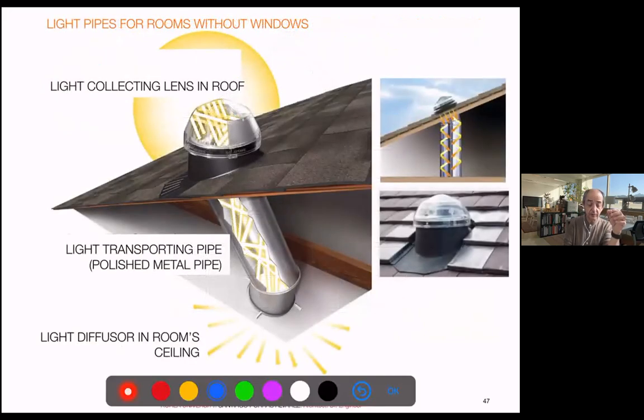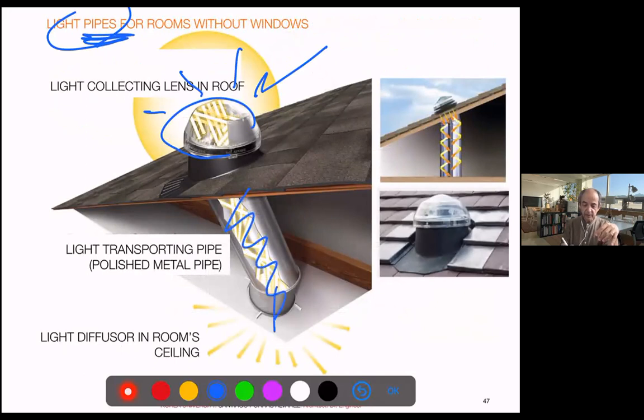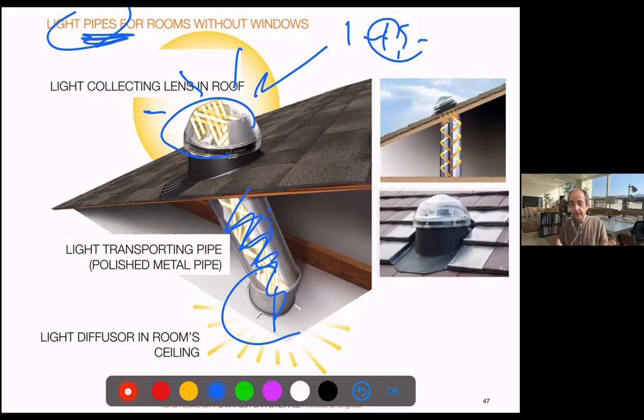Another thing which is interesting is light pipes. Over a small distance, you may have a lens which collects the light from the outside, and a very reflective pipe, which may give light to a room between 1 and maybe 4 or 5 meters from the roof, even lower. You have natural light, almost perfect, with the whole spectrum of light. I say almost because many of the light waves are already absorbed by the mirror, so depending on its quality, the light will be better or worse. But this is quite a cheap alternative to give natural light to rooms where it is otherwise impossible.